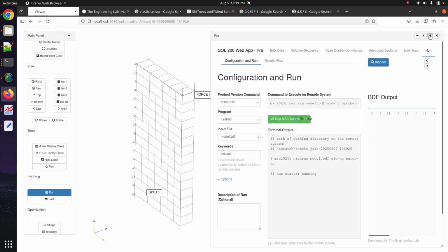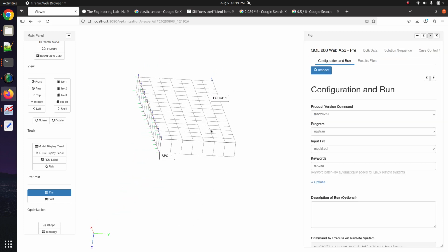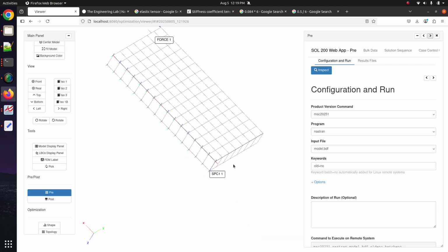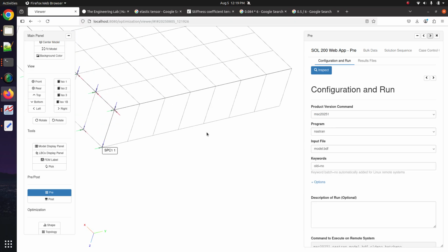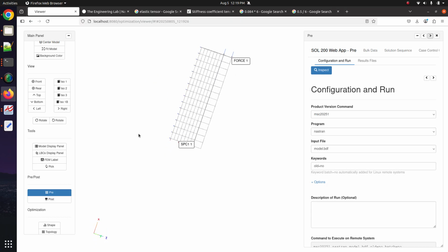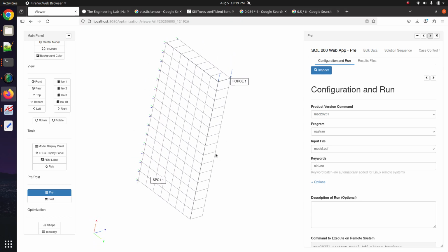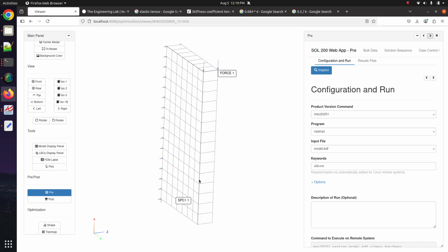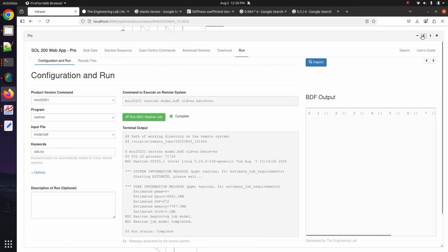The whole goal in doing this was to analyze this new configuration. The original model had this: they fixed it on one end, and then they pulled it with the payload 4 here on these element faces. What I did was constrain one side and then apply a force here. So we're having this bending, if you will. When you have bending, you now have to use multiple elements through the thickness. That's why I'm going through the trouble of doing all this.